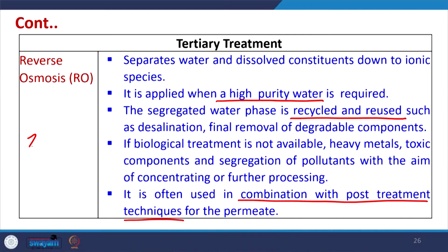That means all those industries which have been told that they cannot discharge any liquid. ZLD means zero liquid discharge. So, if ZLD has to be implemented, that particular industry will most likely be using ultrafiltration, RO and a multiple effect evaporator.